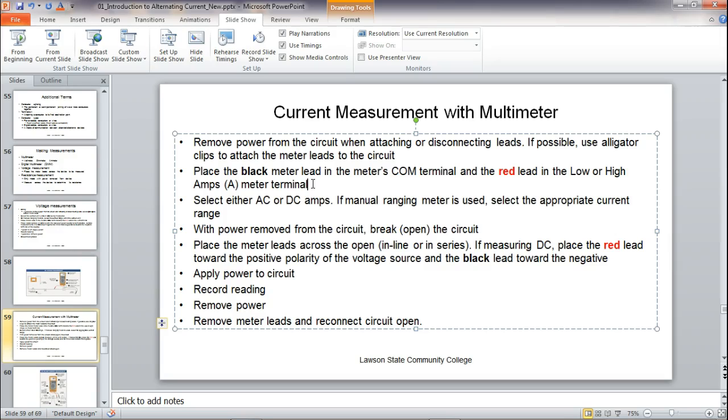Most of your digital multimeters, not clamp-on amp meters, usually have two individual terminals. What we normally do, if we don't know what the current is but we know it's less than the meter range, is put it on the amp setting, make a measurement, and if it gives me less than 1, then we would turn the meter off.